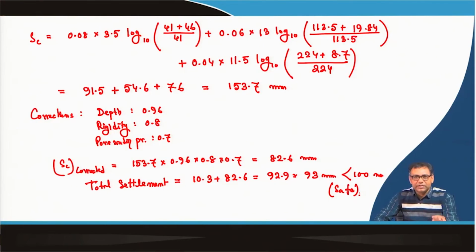Because the scope of this study is to introduce soil foundation interaction, it is not a total course on soil foundation interaction. So I have given the concept, but remember that sometimes the beam concept alone is not sufficient and you have to go for the plate also, but the concept is similar. That means the concept given for the beam you can use for strip foundation and combined footing, but sometimes you have to extend your beams on elastic foundation concept to plates on elastic foundation by using the same concept. So remember that before you do the check considering soil foundation interaction.